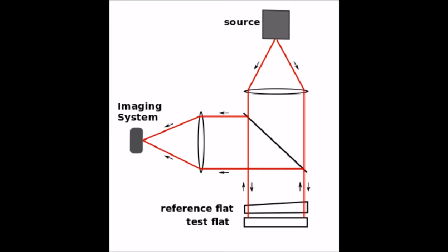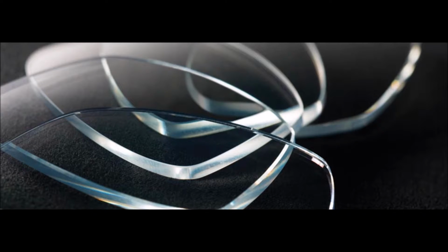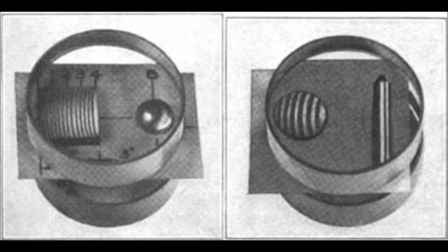In the mid-1800s, Armand Fizeau experimented with an interferometer that resulted from light interacting in various mediums, and he even experimented with the interference formed when two surfaces touch each other. A simplified version with just a viewer viewing the fringes off-axis is used by opticians to qualitatively measure the difference in shape between optical flats. They express flatness error as a result of the spacing of curved fringes formed between the test flat and the reference flat. Machining has also used Fizeau fringes to measure the accuracy of the gauge blocks that they create.